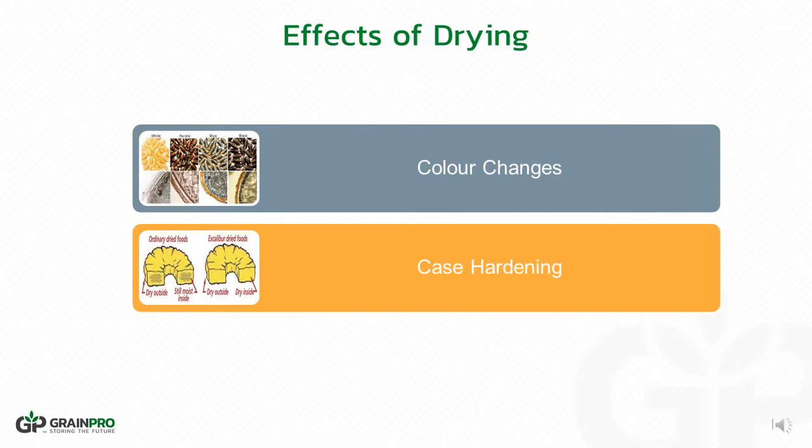Moisture is removed quite rapidly from the surface of the material. It may be removed so fast that the hot air starts to make a hard dry layer on the outer layer due to the collapsing of cells at the surface. This hard layer severely reduces the efficiency of the drying process and may prevent the trapped moisture from escaping.